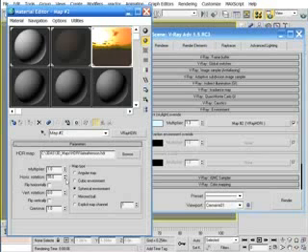By changing the horizontal rotation value, you can see that it changes the part of the HDRI visible in the sample slot. So if I rotate the map 360 degrees, the map will return to its initial orientation, which was 0 degrees. I can also rotate the map vertically, though the practicality of doing so is not as great as rotating the map horizontally around the z-axis.